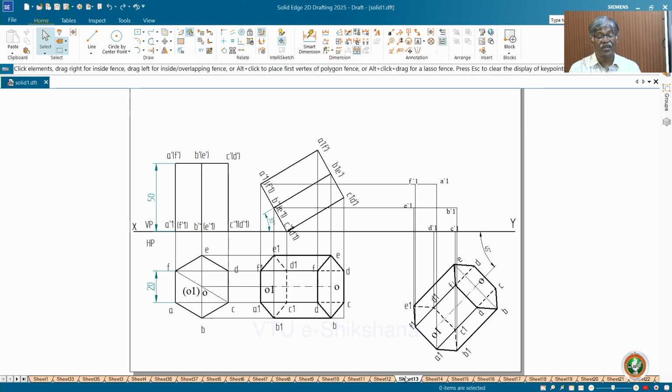That's all. Now, what I do is, after identifying beta equal to 45, I have taken only base corners and projected from base corners of the previous front view. Sometimes what happens, people keep these projections and draw the projection from the top face, they will get different answer, wrong answer. So be careful. I will show that also in future. What happens if you do like that?